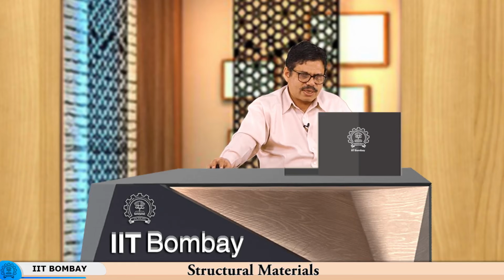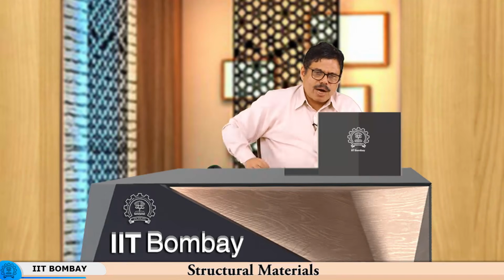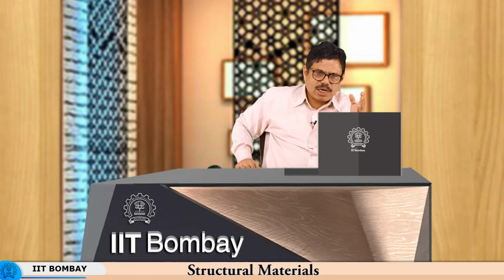If you quench from 600, some austenite will be remaining, and that retained austenite again will become quenched martensite, and then you will have two phases, pearlite and martensite. Here you will have entire quenched martensite, which when tempered at 740 degrees centigrade for about 45 minutes will give you what is called tempered martensite, meaning that part of the carbon of martensite will come out and form carbides.